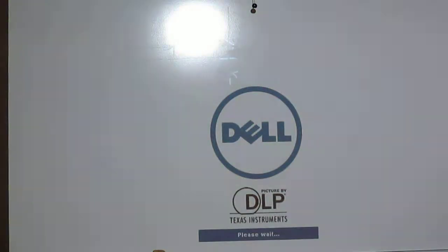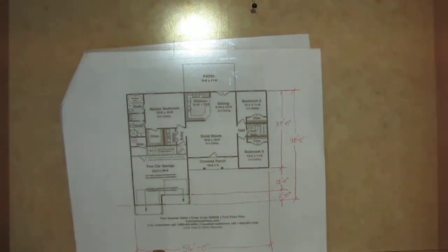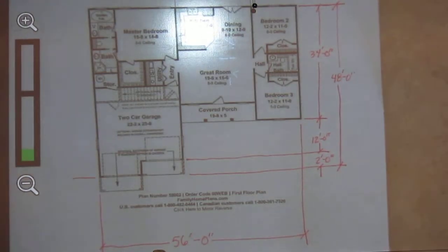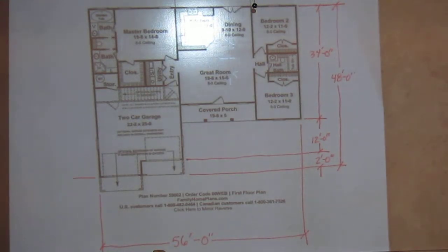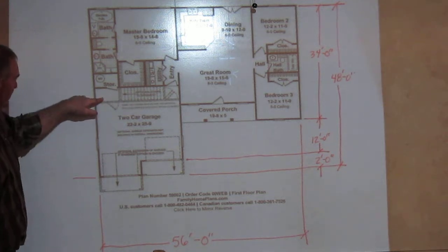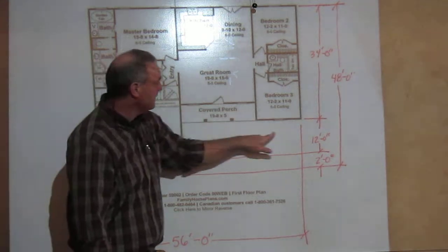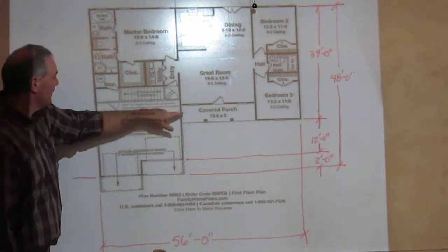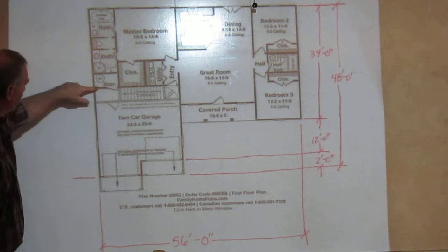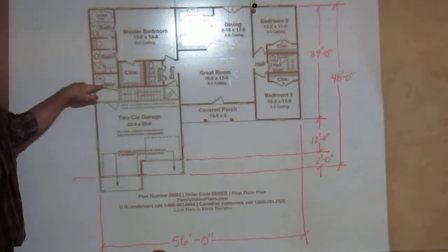So I want to point you out a page. Okay, so I'm on your floor plan. We're going to draw this exterior, and we're going to go 2x6. Right now, we're not going to put a stairway in, so we're going to go 2x6 all the way around this thing on the exterior, and we'll also go 2x6 on the garage house common wall.